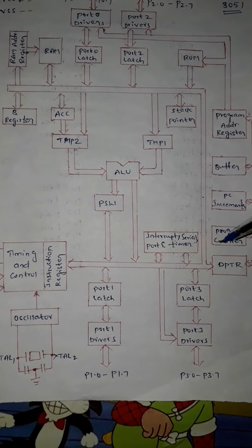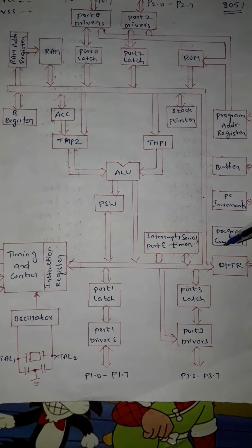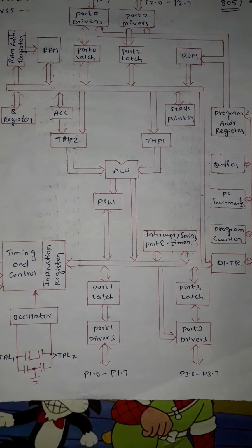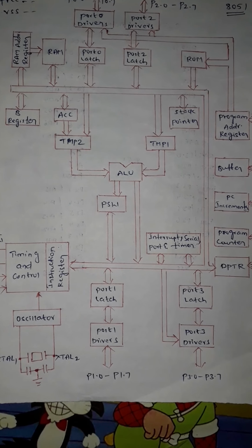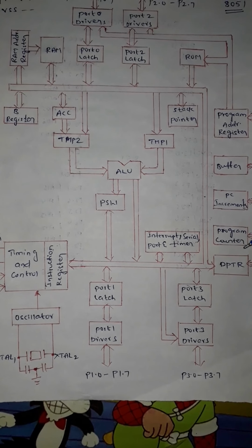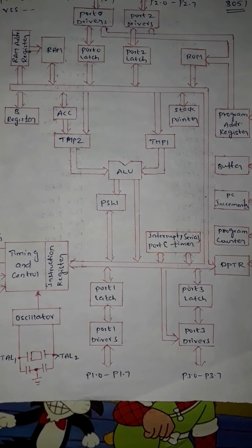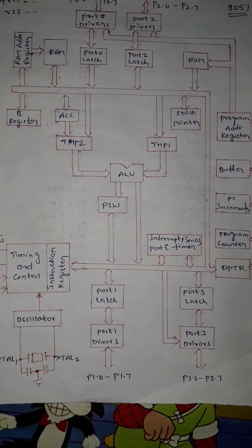So you can access 8 bits of the DPTR, or you can access all 16 bits. DPTR is used to provide the addresses for the external RAM memory, that is, for external RAM access, DPTR provides the RAM addresses for the data.